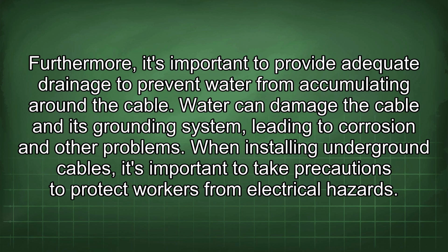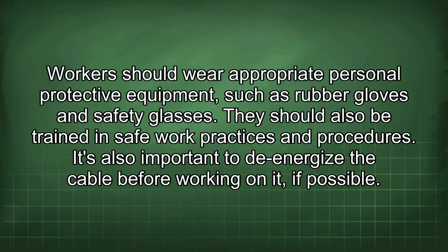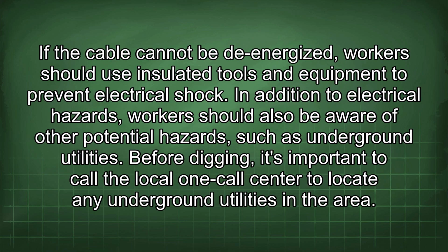When installing underground cables, it's important to take precautions to protect workers from electrical hazards. Workers should wear appropriate personal protective equipment, such as rubber gloves and safety glasses. They should also be trained in safe work practices and procedures. It's also important to de-energize the cable before working on it, if possible. If the cable cannot be de-energized, workers should use insulated tools and equipment to prevent electrical shock.